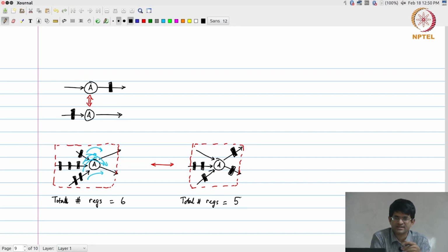Under those constraints, it is possible to set up complete optimizations. You could either try to optimize the critical path and therefore the speed at which the system operates, or you can try and optimize the total number of registers present in the circuit, which in turn is related to the area occupied by the circuit, or in some cases you might even have some other combination of these, right, some other metric that you are interested in, which is the sort of balancing.